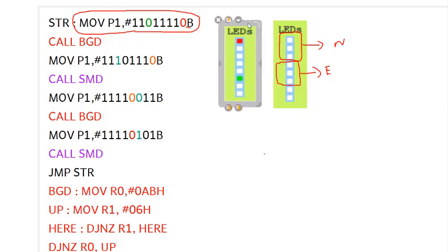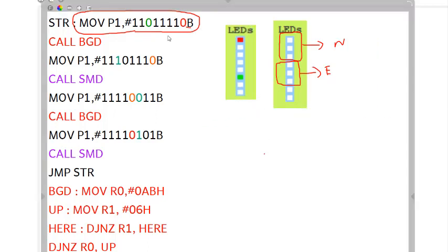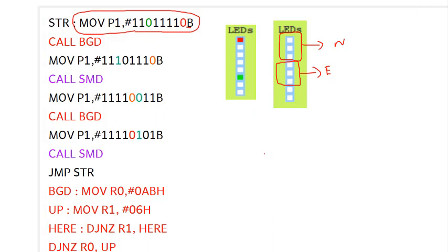This will be the output with this input. Because this is 0, this 0 will turn on this LED, and because it is red, it gives the red signal. This one will ensure that this LED glows, and the green is turned on. Whichever input is 0, it will be turned on. As we can see here, north-south is given the red signal and east-west is given a green signal. So this is what we have with this particular input.